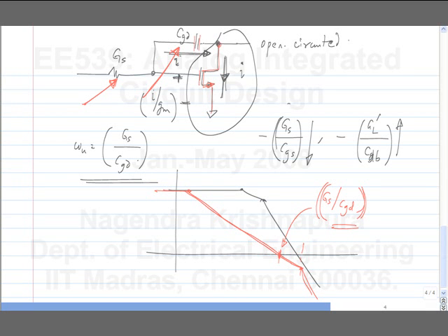This is a right half plane zero. So, we cannot really use it to cancel the pole. The poles will all be in the left half plane. That's correct. Yeah, we'll come to that soon. So, we can have other techniques where either the zero goes away or we can move it to other frequencies. But if the zero is there, it is not a good thing because this is a right half plane zero, which tends to give you extra phase lag.